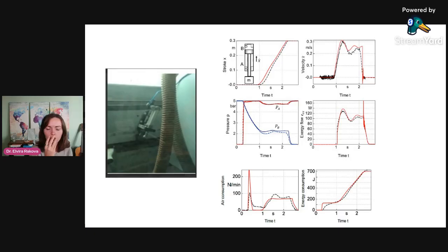Of course, you can think, okay, the piping in the main header, from the compressor until the machine, is also kind of a reservoir, but it's actually not. Physically you have a demand side where the air is needed, and the air has to pass through this. And of course, the sizing of this is extremely important. Oversizing of this might only lead to higher cost. However, we always need to understand what the maximum demand is going to be.